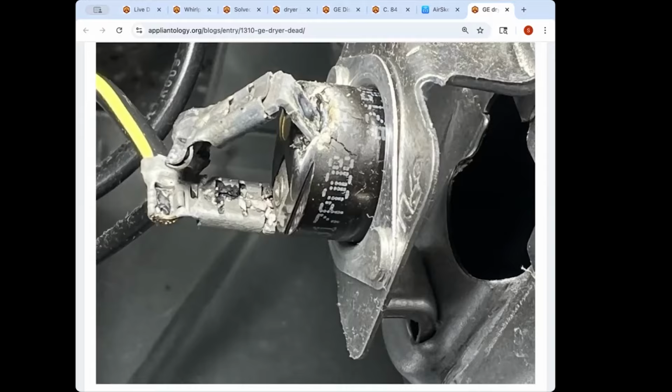A good example would be the GE dryer with the heating element on the back wall, where the purple wire always burns off at the terminal. They've changed that now to where they actually have a replacement wire for that that's a different gauge wire, and you now actually have to depin it from the connector at the motor and put that new one in there. That's from the manufacturer, so they made mistakes. So we can't discount stuff like that.